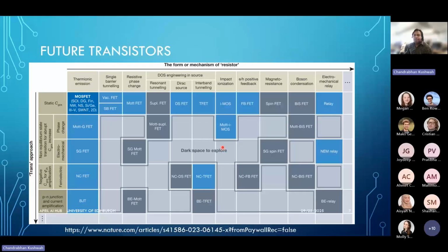However, there is a trade-off. These new mechanisms often introduce hysteresis and a kind of memory effect, which limits their use in fast logic-based computing. Still, they show strong potential, especially in memory applications and energy-efficient circuits, especially tunneling FETs, TFETs, revisiting two aspects that they are very good at for scaling technologies.